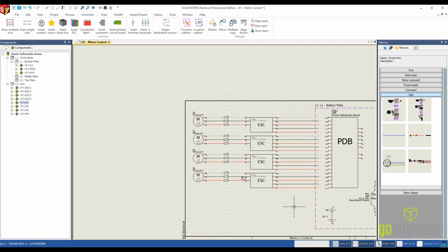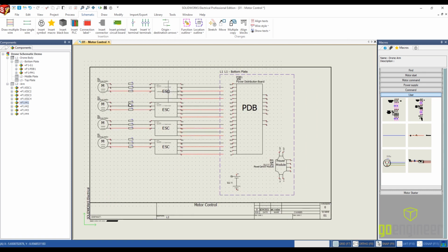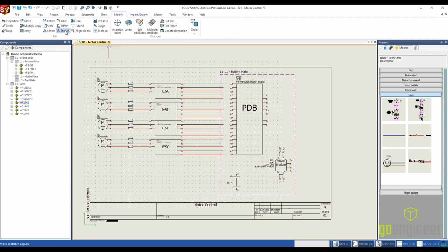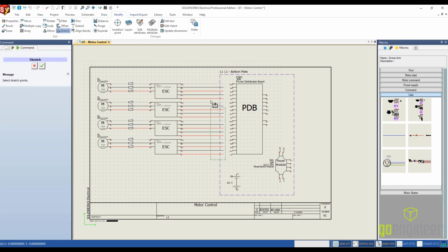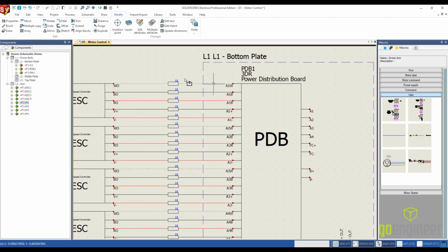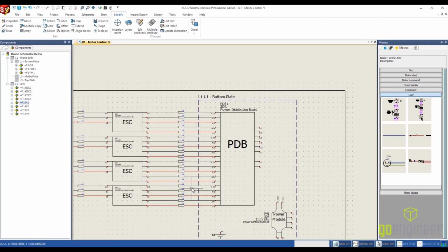All right, so now we have everything that's related to the arm there. But now I need to make these connections. So I'm going to go ahead and just do a modify and stretch. So what we want to do is just stretch these wires and make them connect. So we've got our points there, and then I can just make that connection. And now you see that the connection's there because my wire labels pop in there as well.